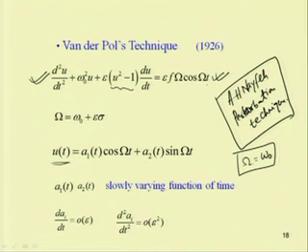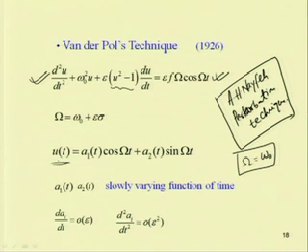So, this u(t) we have considered is equal to a₁(t) cos ωt plus a₂(t) sin ωt. The amplitude of vibration will be the square root of a₁² plus a₂². Or one can write u(t) in terms of a single term, a cos(ωt plus φ), and the amplitude can be found from these two expressions.